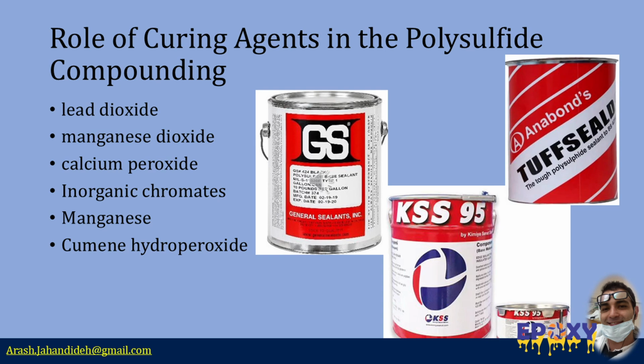One-part sealants commonly use calcium peroxide as the curing agent because it remains inert in the absence of moisture. Barium oxide is included as a dehydrating agent just before adding the calcium peroxide paste. This helps the package stay stable by absorbing water molecules.